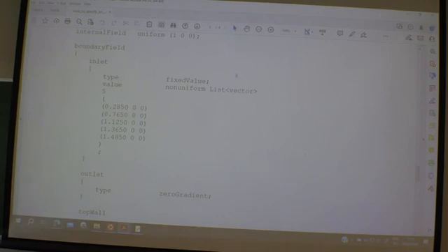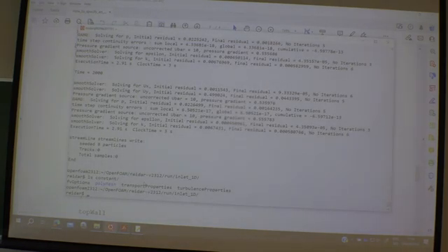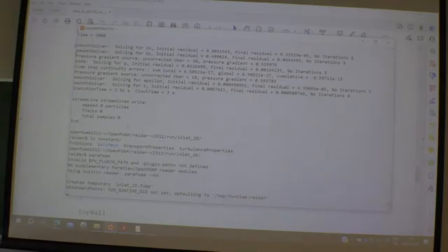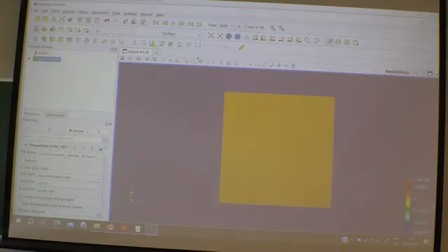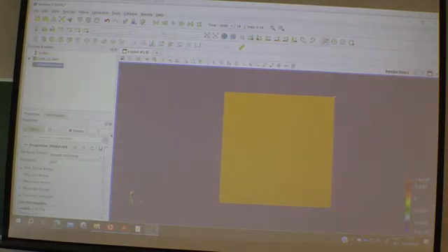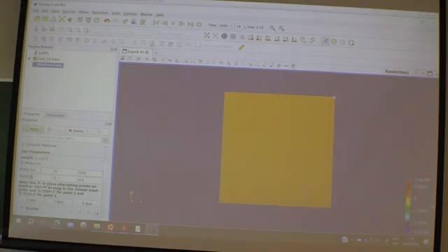How does it look? Quickly, we have time for that. Let's see now. ParaView. Apply, go to the end, take a plot over line, and I want it from x point 0.5, 0.05, 0.5, 0.05.